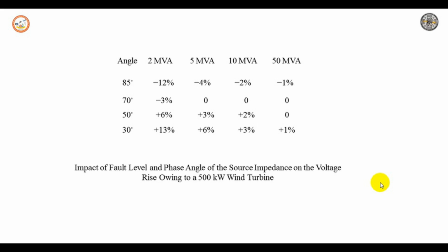very close to 250 volts at the start of the feeder, about 252 near the middle of the feeder, and at the end you see 253. There is a significant increase of 1 volt in every section. This could be a concern when an over voltage limit of only 110% is used. It should be noted that a 95 mm square cable would give a voltage rise about 3 times higher. So this results in a maximum voltage of around 258 volts, or 112%.